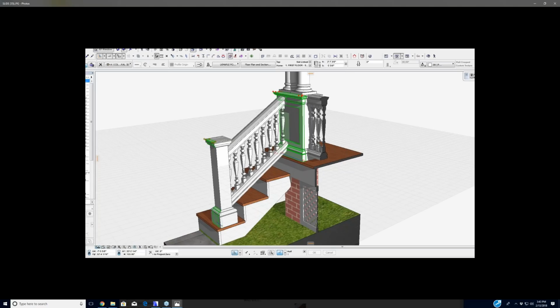Now, I might have turned it into a morph because the morphs were easier at the end to punch an opening like that. A complex profile is going to run continuous. I would use a solid element operator. I would have a slab floating in space as a solid element operator, meaning it only shows up when I'm in my modeling version of this. It's not going to show up on the plan. Then I can highlight this, go through the application of deleting that, and leave that solid element operator where it is.